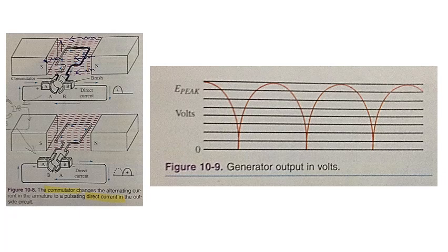When the armature revolves 1/2 turn, the induced current will reverse its direction. However, the commutator sections have also turned with the armature. The induced current flowing out of commutator section A is now in contact with brush B. This current flows through the external circuit to brush A into commutator section B, completing the circuit. The current flows through the external circuit in the same direction both times.